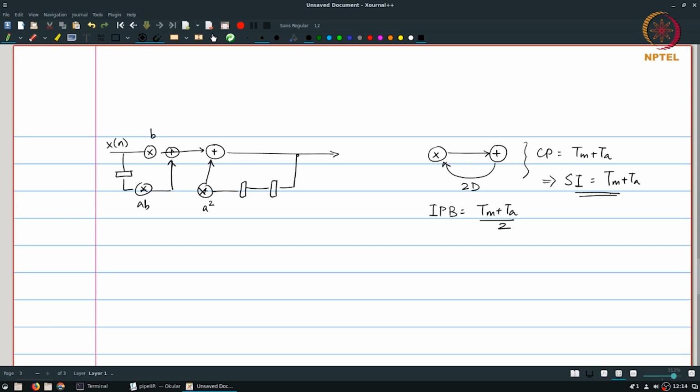As before, there are two things we can do over here. One is, if the multiplier and the adder have more or less equal delays, then we could just use a pipelining transformation over here. And yes, this is perfectly legitimate and would work fine to reduce the time taken inside the filter, or in other words, to increase the throughput of the filter. The other alternative that I could do would actually be to do an unfolding transformation once again.